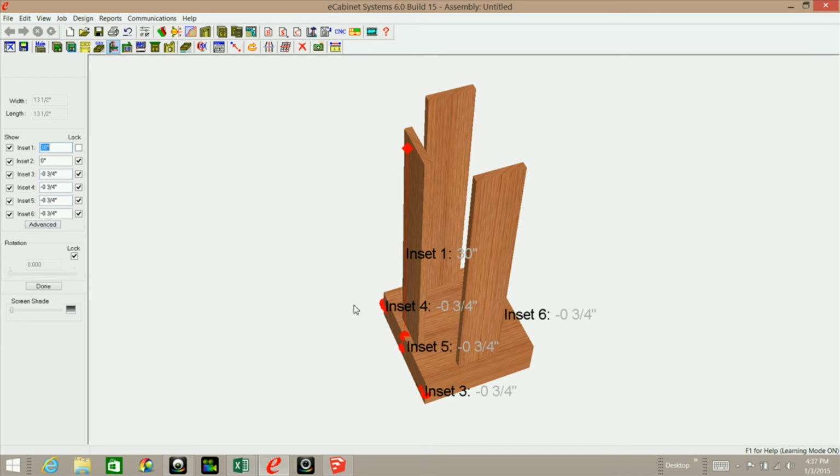But what's going to happen then is you're going to get a message saying that there was a problem generating constraints. You're going to lose your constraints, and you're also going to lose all your part editor cuts. So if you plan on using certain thickness material, make sure you draw it up first with that. And as you saw, it's not really that difficult to put the geometry back on.